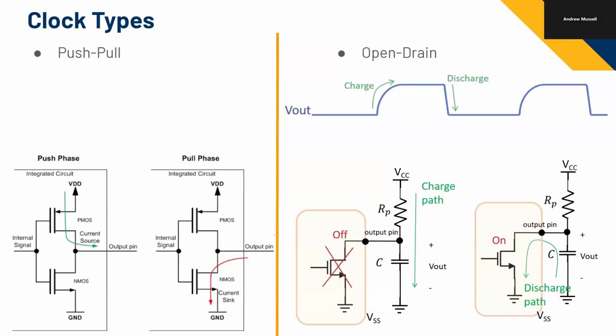You have power over a resistor to the capacitor, and so you're burning some power there, because the power dissipation of a resistor is V squared over R or I squared R. So some energy is turning into heat. But that's what gives you this waveform on the top right where it'll charge and then discharge.